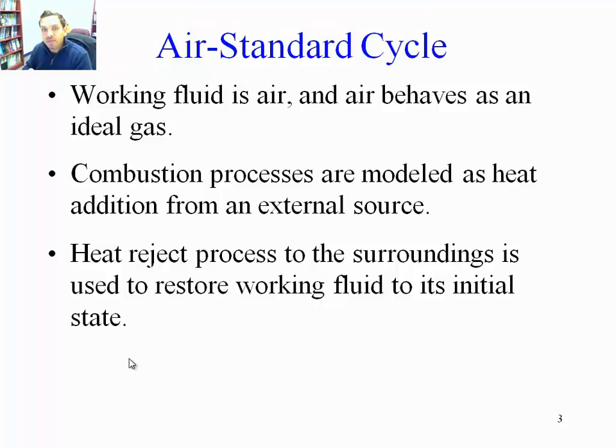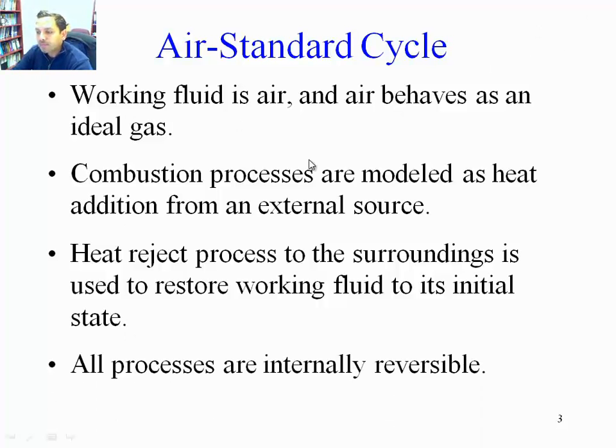So instead of saying, well, we're going to take that air, dump it to the atmosphere, grab new air, and restart the cycle, we're going to say the air is cooled down by a heat rejection process, and then the whole cycle starts again. That way we can analyze the whole process as a thermodynamic cycle. And we assume that all processes are internally reversible, unless otherwise specified, basically that there is some entropy generation or some irreversibilities.